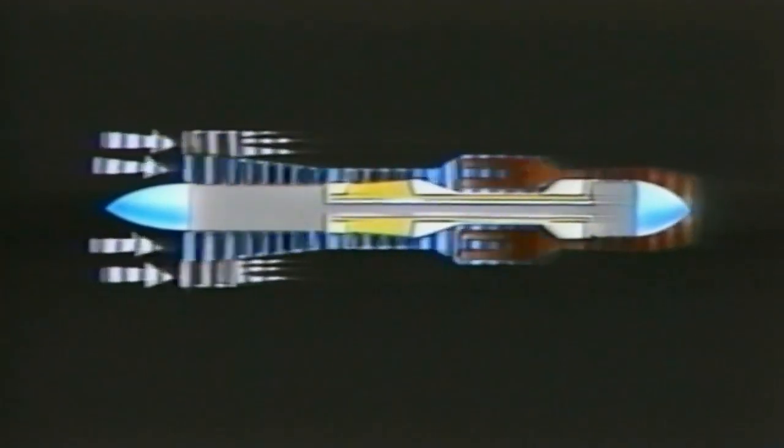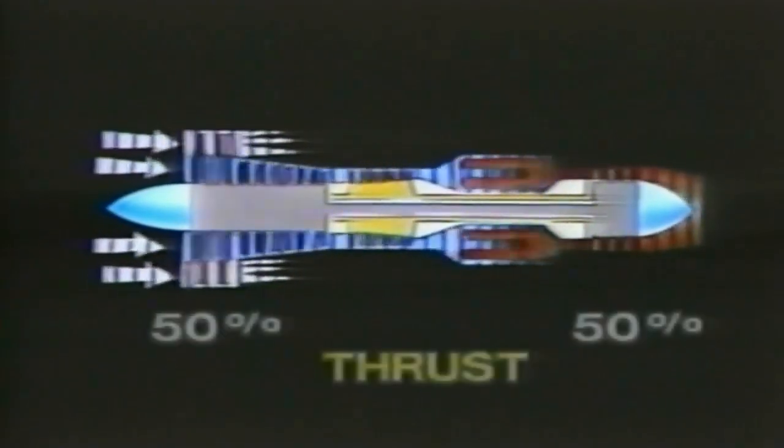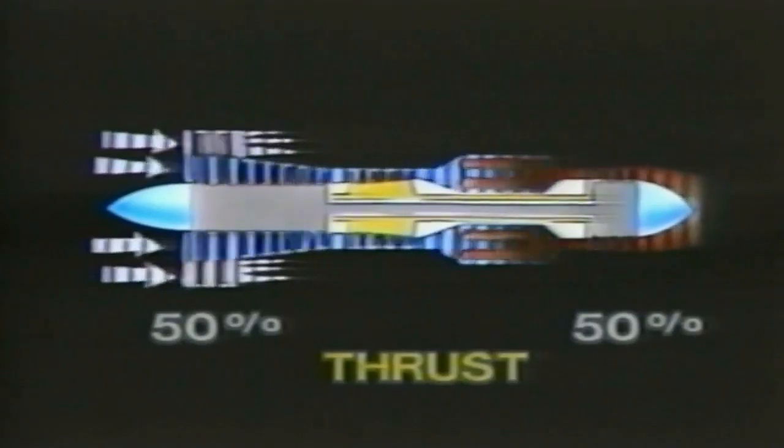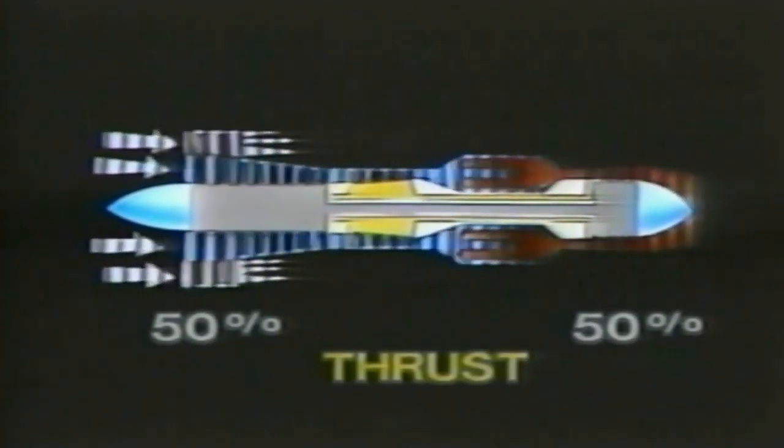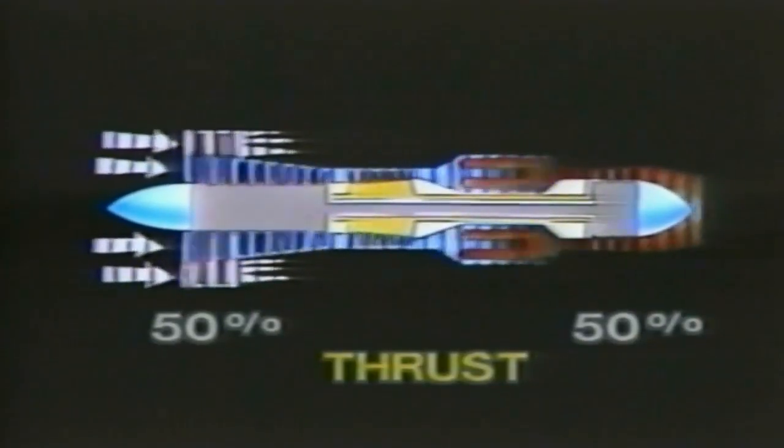They draw in an additional mass of air, accelerate it, and then expel it from the exit of the fan section, thereby producing a separate additional source of thrust. It takes a lot of power to rotate this low compressor with the added fan blades, so the low pressure turbine must be large enough, have enough stages to do the job. So the gas generator with its jet nozzle contributes to the overall thrust, and the fan contributes too. How much? For a ballpark figure, let's say 50-50.